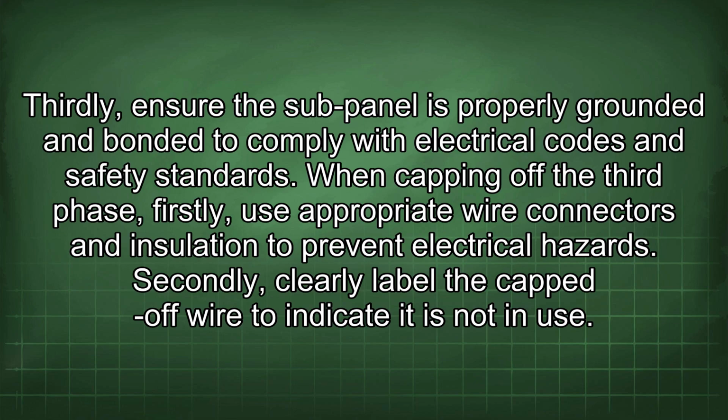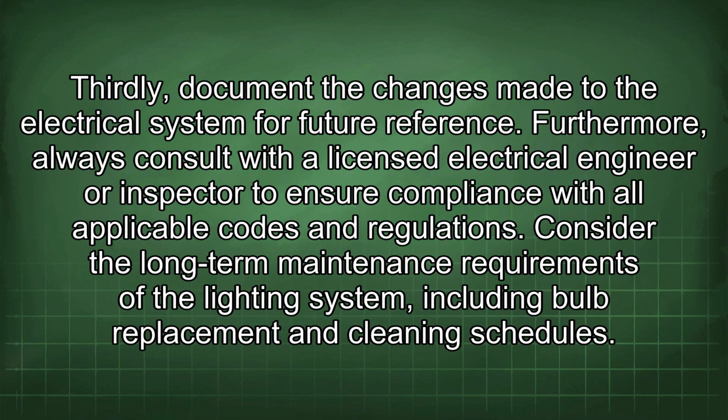When capping off the third phase, firstly, use appropriate wire connectors and insulation to prevent electrical hazards. Secondly, clearly label the capped-off wire to indicate it is not in use. Thirdly, document the changes made to the electrical system for future reference. Furthermore, always consult with a licensed electrical engineer or inspector to ensure compliance with all applicable codes and regulations.